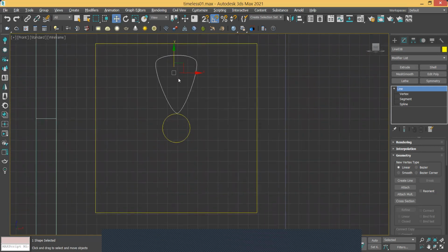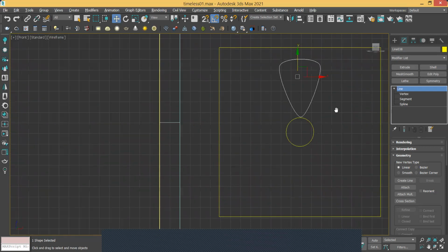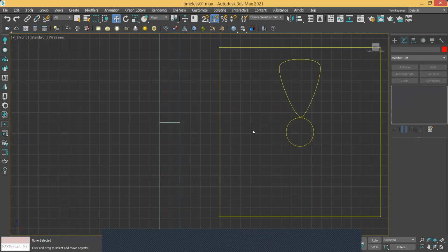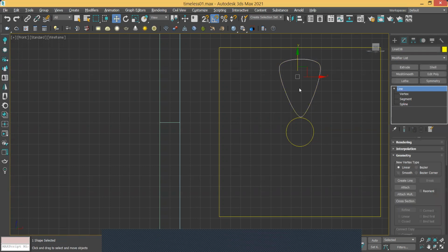Let's see how we make multiple copies of the petal. We're going to use the array command to make copies for multiple petals, and to choose an option which is instance, that helps us in changing one element so as the rest will be changed automatically.